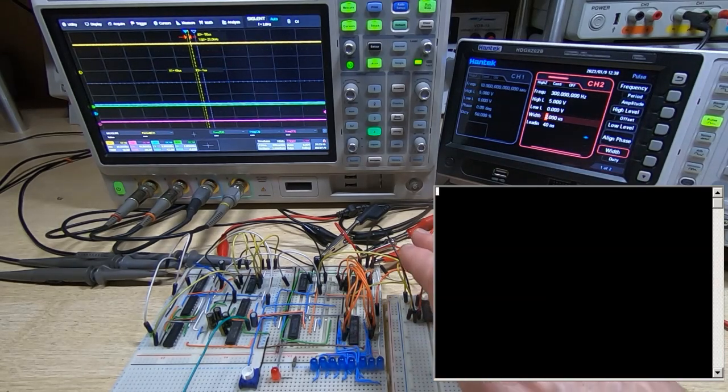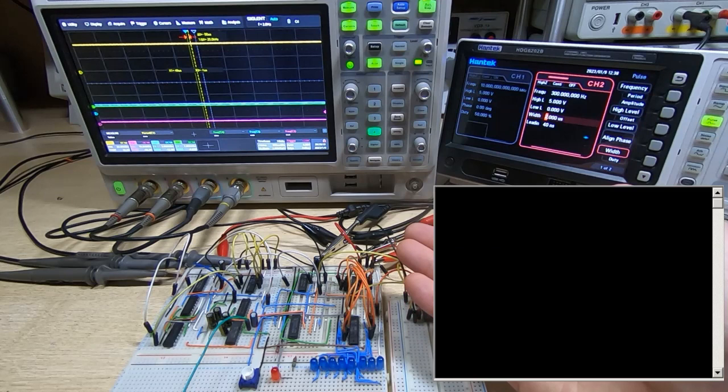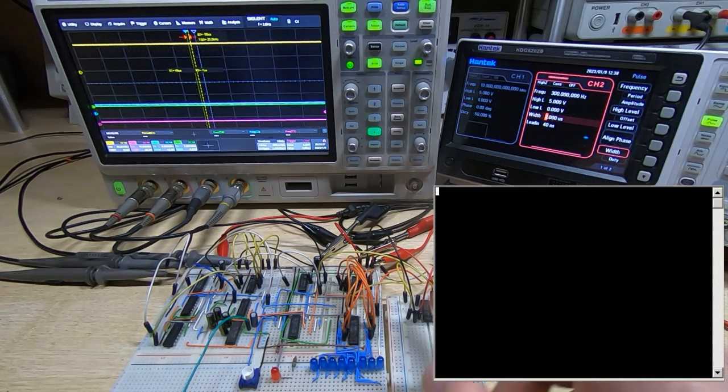This circuit on the right here is really the clock divider circuit that normally resides on the Z80 board. It's the primary divider coming from the clock, but I've included it here just so I don't have to have the Z80 board hanging off the end of this. It's providing at the moment the 625 kilohertz clock to the circuit. It's fed with a 10 megahertz signal, which is equivalent to our 10 megahertz crystal on the main board, and it's just divided down to give us the 625 kilohertz clock signal.